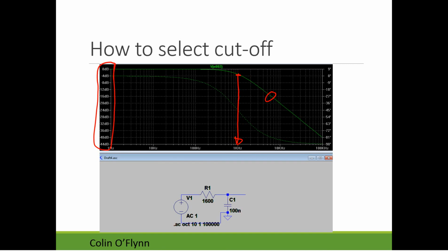And if you say, well, I have a 10 kilohertz source at some amplitude, how much will it be attenuated? This is the issue: we have some other power, and we want to make sure of that 10 kilohertz source. You can read off that it's going to be diminished by minus 20 dB. We can go back to the charts, or you can solve for this to figure out what the actual ratio of power that will be diminished is, or what the ratio of the voltage change is.